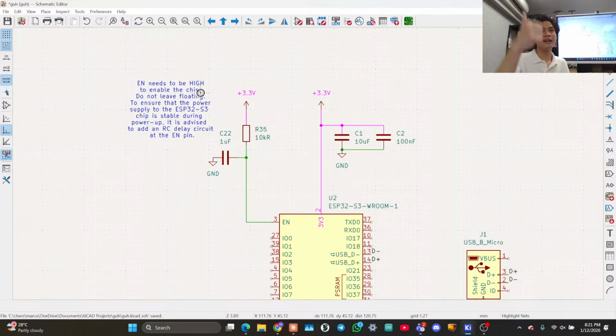Okay, everyone's happy? Also, the two 3.3s don't connect to 2 different 3.3s. No, it's all shorted together because they have the same net name. Right? Yeah. If let's say you want two separate ones, then just name it 3.3_2 or something. Yeah, some funny thing like that. So sometimes we do that.